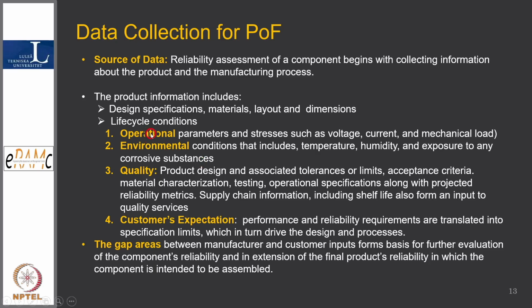So we have to take the life cycle loads and the operational environment together, and then designate how long this will be in use. Then quality, as I mentioned: quality in product design and associated tolerances, limits, acceptance criteria, material characterization, testing, and specification along the project, and reliability metrics, supply chain information, including shelf life.